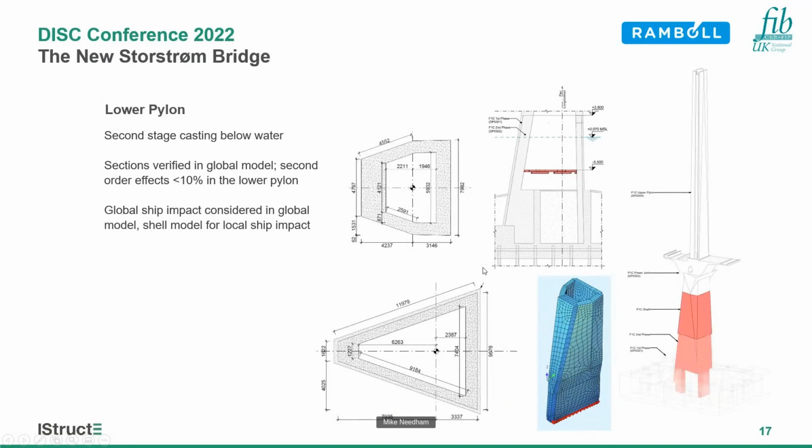The lower pylon is an interesting tapered shape. It needs a second stage casting below water level. It was designed primarily from a global model, but second order effects were evaluated and found to be less than 10%, so not particularly significant. What was significant, however, was the global ship impact, which is up to 65 meganewtons, and that required a shell model to look at the local ship impact and also some quite advanced dynamic analysis, which we'll talk briefly about later.